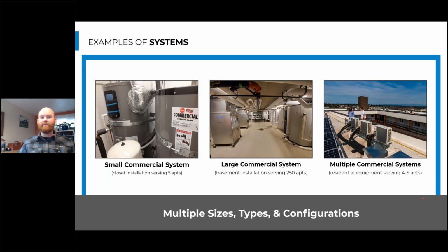And then these systems come in various different ways. We can do a very custom system or a very packaged system, but they also come in different sizes, types, and configurations. We can connect the storage tanks differently. We can connect the heat pumps differently to get different configurations. We can also use different types of heat pump water heaters, a single pass or a multi-pass heat pump water heater, or heat pumps that use one refrigerant over another. And they come in a variety of different sizes as well.